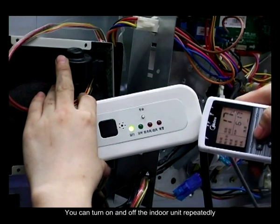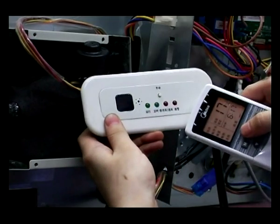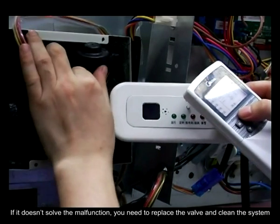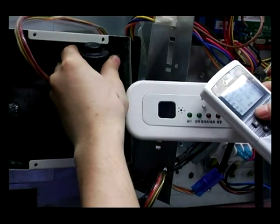You can turn the indoor unit on and off repeatedly and feel the action of the throttle part and refrigerant flow by hand. If this doesn't solve the malfunction, you need to replace the valve and clean the system.